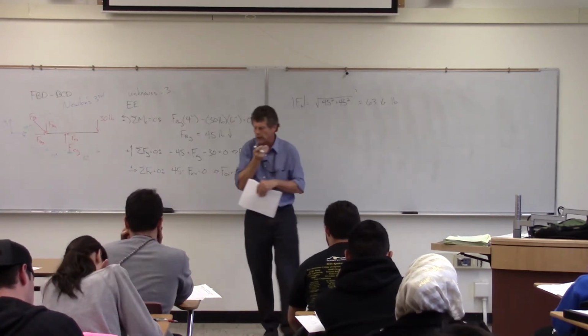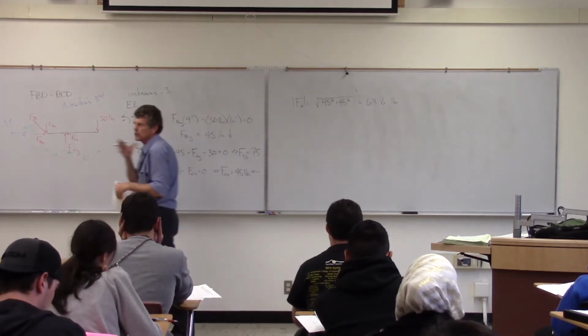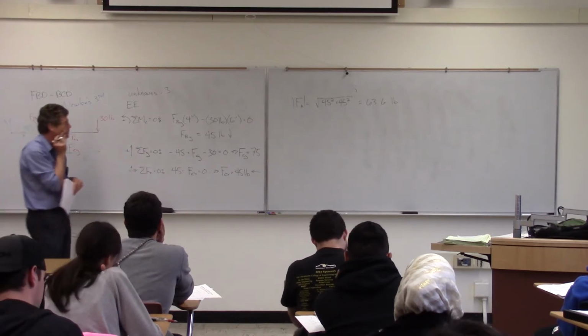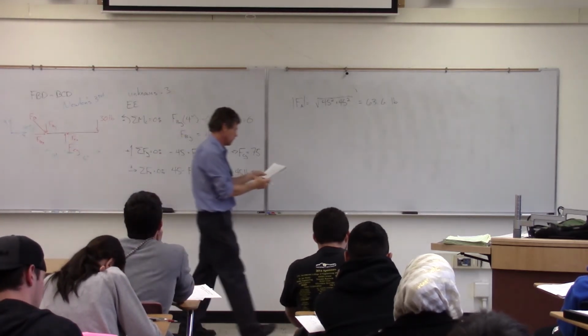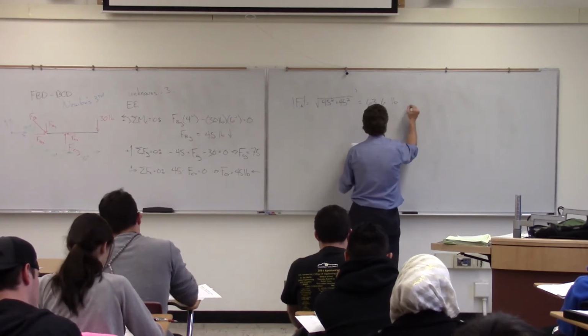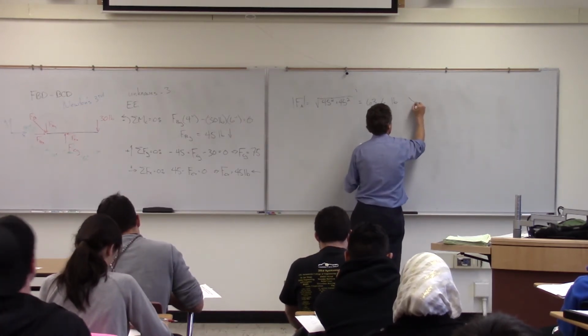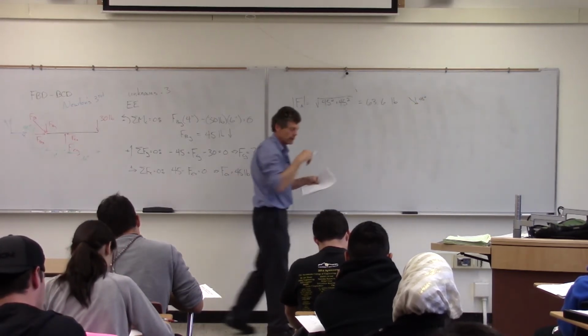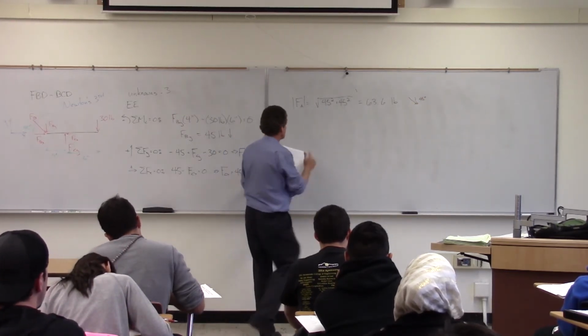Again, if I'm looking at a pin, I'm really going to be interested in what the full load is on that, not the X or Y component. So we want to solve for the full amount there. It'll be acting at minus 45 degrees.